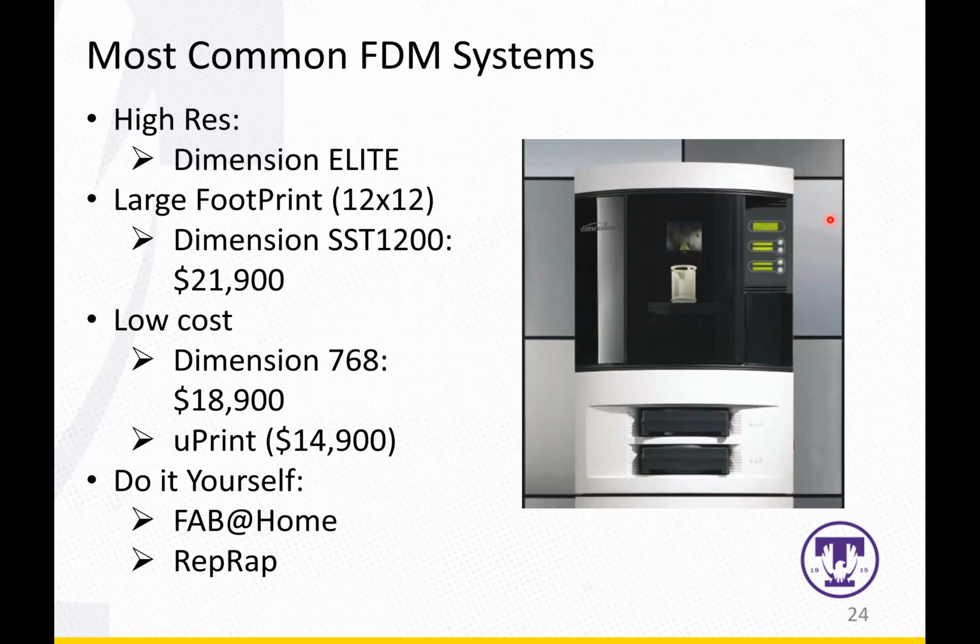And here's another high-end machine. As you can see, this one has a room for the printing. So it might have better control of the temperature, the thermal control. That's why those high-end machines usually generate parts with better surface finish and high accuracy, and their reliability is much higher because they are carefully designed. All the mechanisms for feeding and for the extrusion are much better than those of the consumer-level ones.